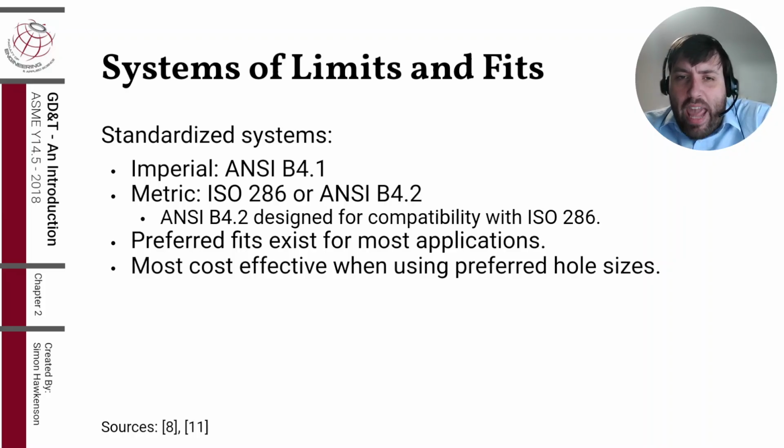Parts designed to ANSI B4.2 specifications are almost always interchangeable with those designed to ISO 286 specifications if the same tolerance classes are selected. Both systems have preferred fits to select from the list based on your particular application.